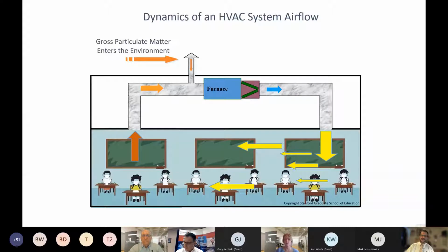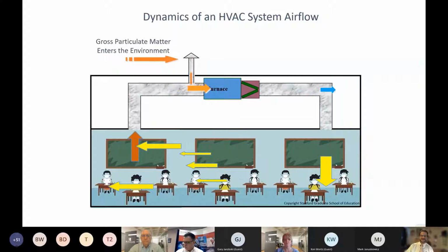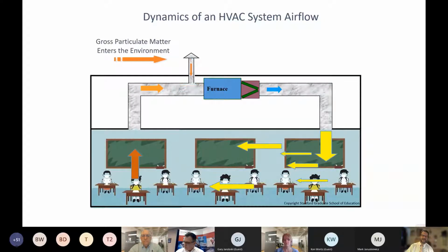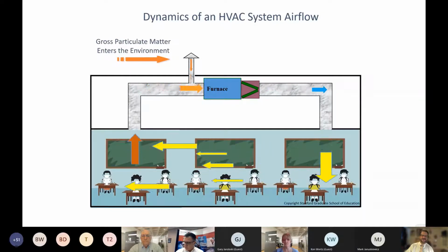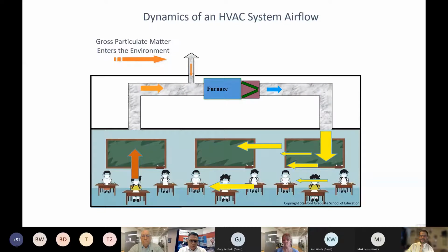The other thing we're concerned about is in those classrooms that do have ventilation systems with air conditioning systems, sometimes, depending on where the students are sitting, the airflow is flowing in one continuous manner, and I'll explain this in a minute by looking at some of the air conditioning registers. The airflow is flowing from one side of the room to the other side of the room. This could be problematic too, with the spread from an asymptomatic COVID person to other people.